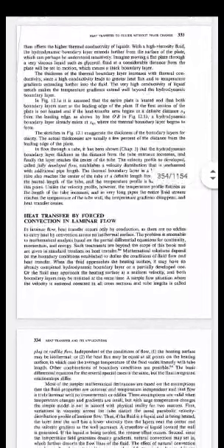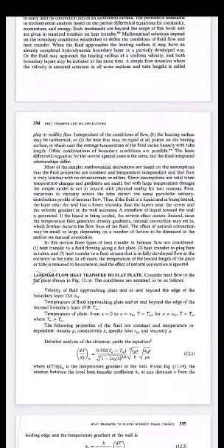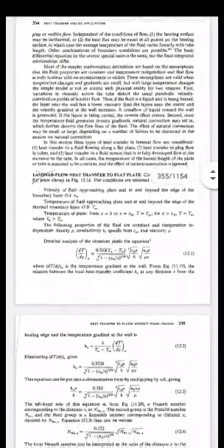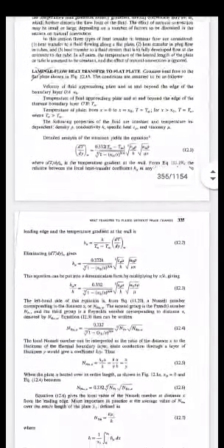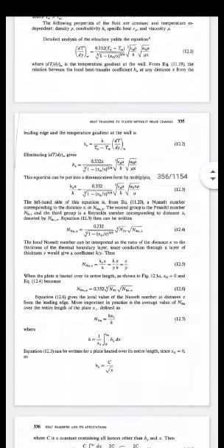After that we went through heat transfer by forced convection in laminar flow, where we saw three cases. The first case was heat transfer to a fluid flowing along a flat plate, another was heat transfer in plug flow in tubes, and the last case was heat transfer to a fluid stream after fully developed flow at the entrance of the tube, where we went through equation 12.1. After deriving this equation, we came to know the correlation between the Nusselt number and the rate of heat transfer.